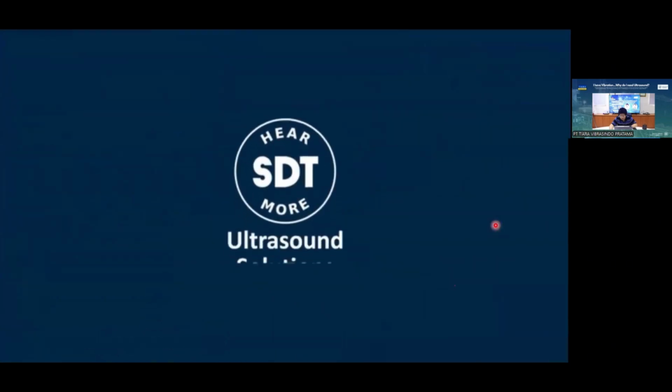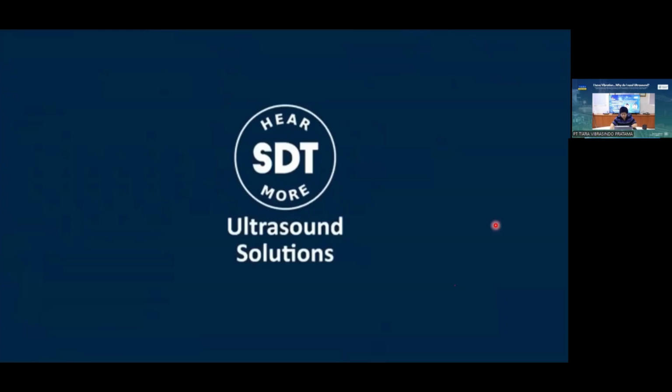It's really simple. How do you know the steam trap is in good condition or bad condition? You just hear the sound and see the amplitude of the decibels. It's going high, it's always closing and opening, close and open. It's okay. This is a good condition because you want to know the type of the steam trap, and you should know how it works. If it closes and opens, it's a cycle. It's okay. It's a good condition.